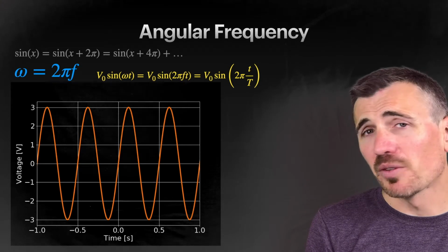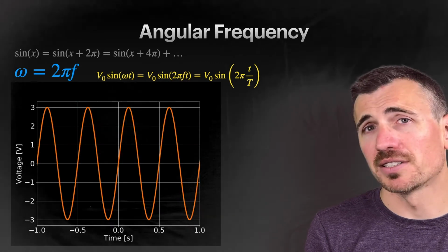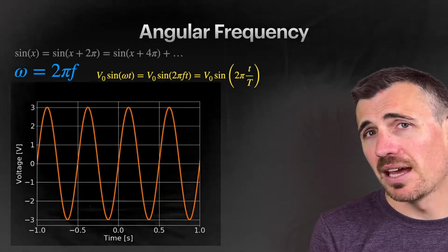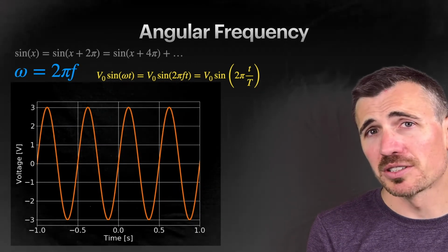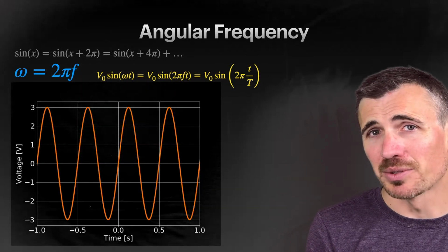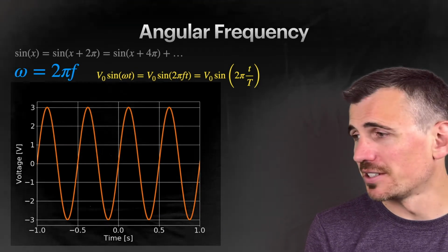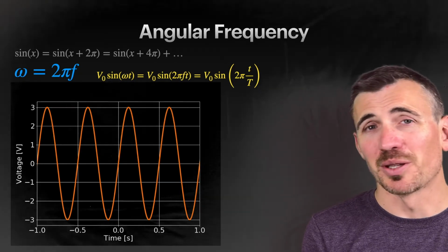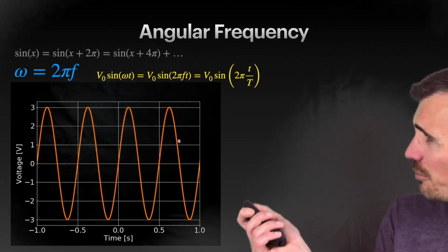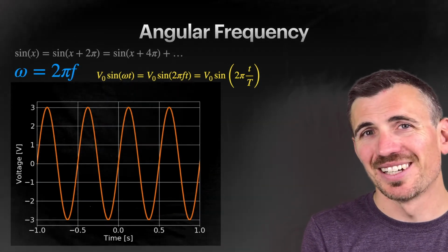Okay, so typical values for electronics start around 10 hertz. The voltage coming out of your wall is 60 hertz, at least in North America. It'll be 50 in other places. And the electronics we deal with will be kilohertz, megahertz, maybe even up to gigahertz. After that, it gets pretty tough to talk about microwave frequencies, which are at terahertz. And it's almost impossible to make circuits work at tens of terahertz. If you go to hundreds of terahertz, well, that's called electromagnetic radiation or light. So I have a laser pointer here. So there's about, I don't know, maybe 700 terahertz or maybe 600 terahertz signal there.